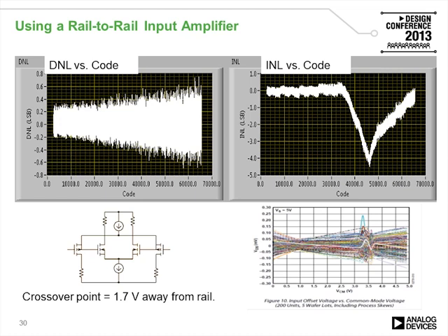In this case, we're showing an N-type and a P-type input stage. When the crossover point is reached, that means when one input stage is used and then we cross over to the other one to reach the other end, there is that small distortion that is shown on the bottom right of the screen.